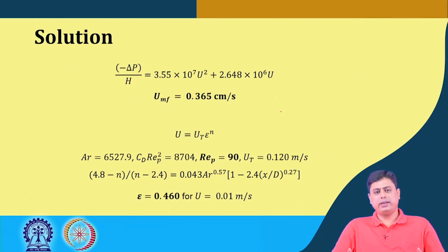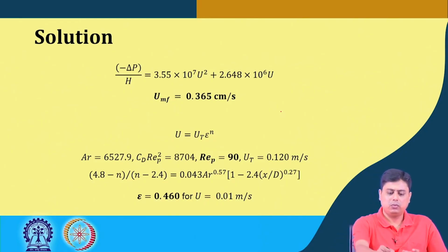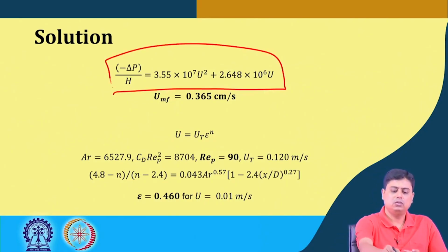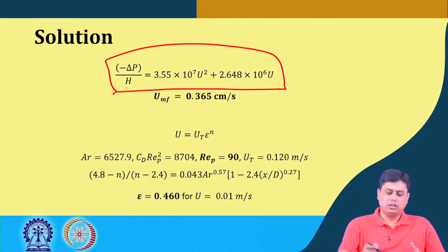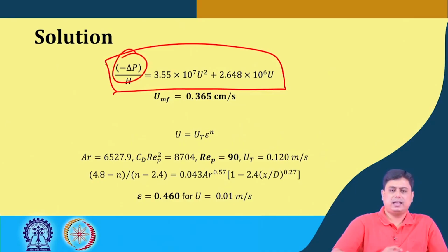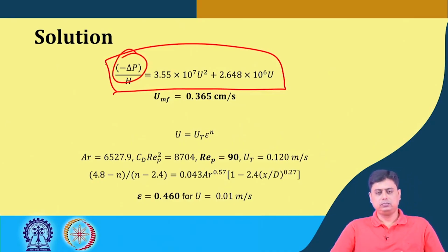Considering that the Ergun equation is still valid, we can apply it, both the inertia and the viscous parts. We can find an expression that involves the unknown velocity term, because on the right hand side this ΔP we have just calculated for the incipient fluidization condition.